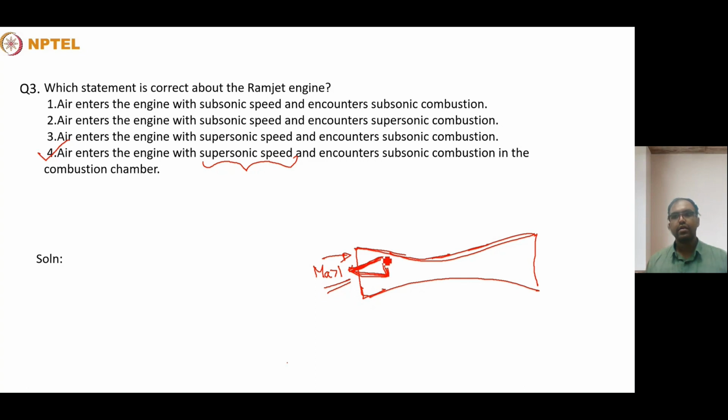whose pressure increases instead of having some rotating device or moving part like a compressor. The presence of the Mach number greater than 1 produces shock waves that will be producing compression to the air. So rather than a mechanical compression, it is a thermodynamic compression. And once it goes through the converging duct, its pressure increases and velocity decreases since this Mach number is greater than 1.